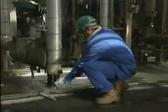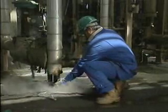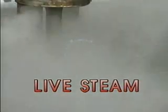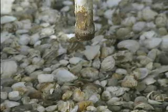Two types of steam are normally associated with industrial steam systems. One type is live steam, which is the steam that's used for heating or for process operations. Live steam is produced by heating water to the appropriate saturation temperature. The saturation temperature is the water's boiling temperature for an existing pressure.